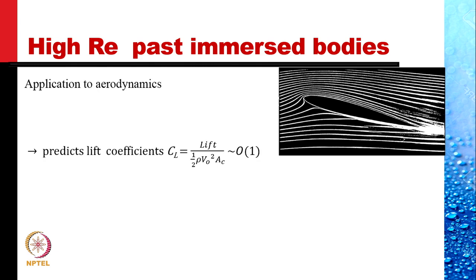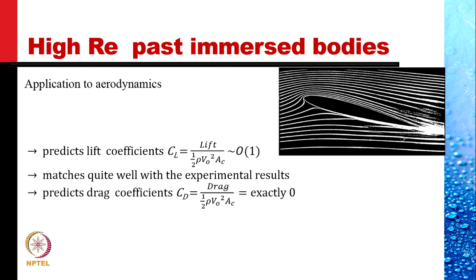So, this assumption of neglecting viscosity when applied to problems in aerodynamics gives good results in predicting lift coefficients. As I said, it matches quite well with the experimental results, and it predicts drag coefficients exactly as 0.